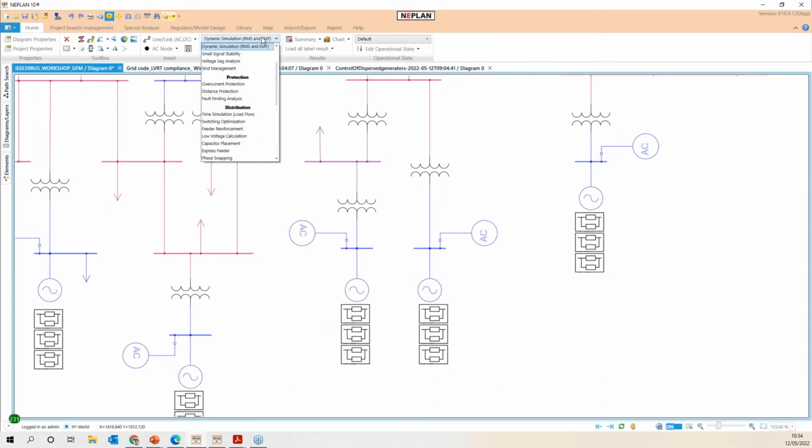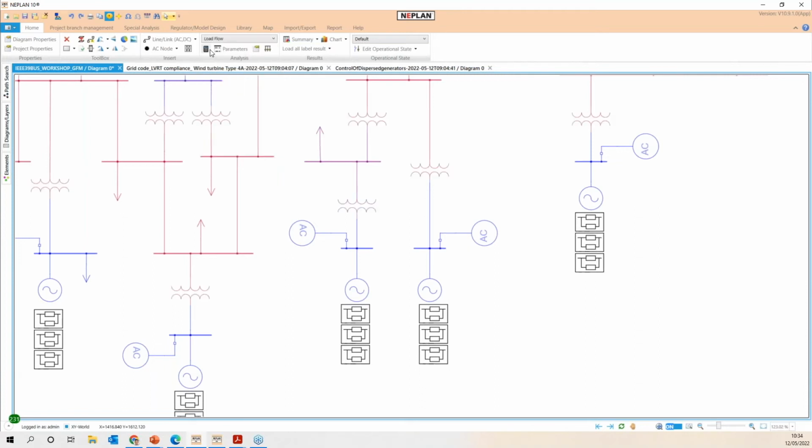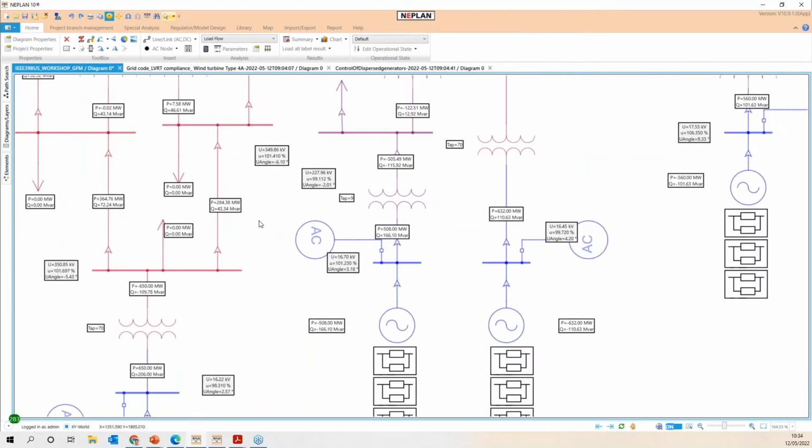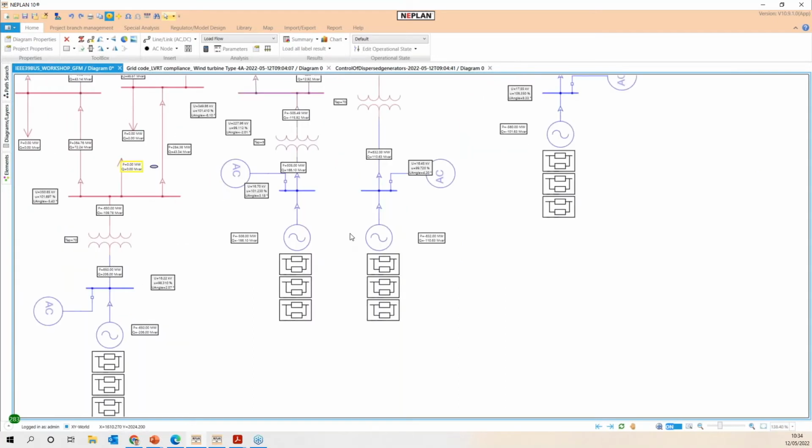The different power system studies required on the grid code compliance are accessible through a list of different available models, like the power flow, which is able to perform thermal analysis to validate conditions during steady state conditions. In this case, we will be able to validate if the system would be able to support the carrying condition of the system.